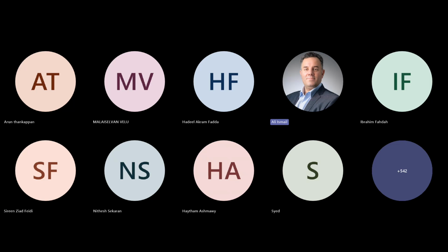The question from Muhammad Kashif is related to the shared parameter. I think this is related to Revit and is a very technical question. It is not necessary to use instance shared parameters. If you think you can make these parameters family or type parameters, please go ahead. At the end, we only need the parameter attached to every door in your case. So do the best practice, what you think is correct in your case, to avoid entering the same instance parameter many times.